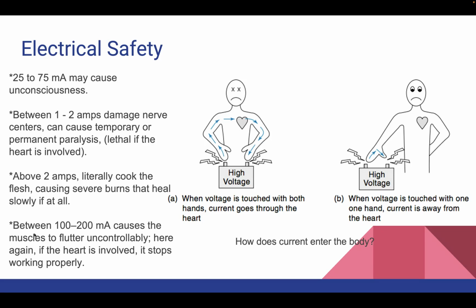As an extra precaution, temporarily jumping the high voltage line to ground can provide protection in case someone turns the power back on. So in that case, if the high voltage is connected to the ground, it can provide some protection.